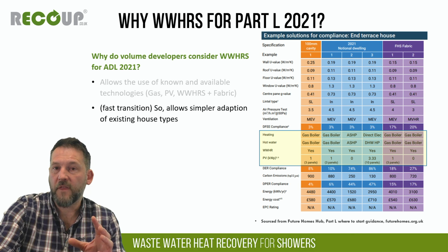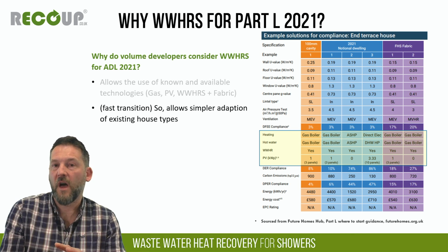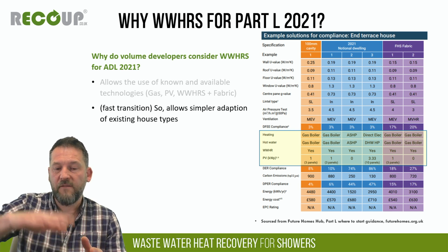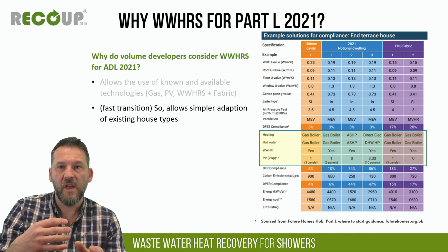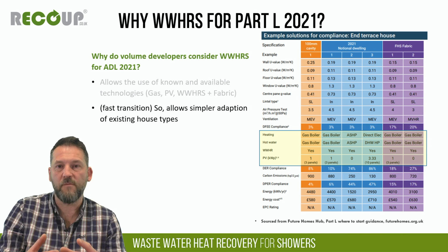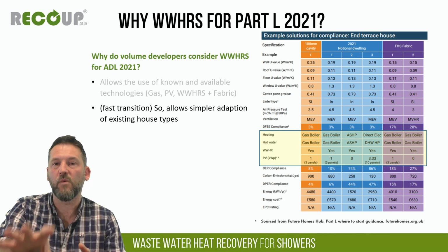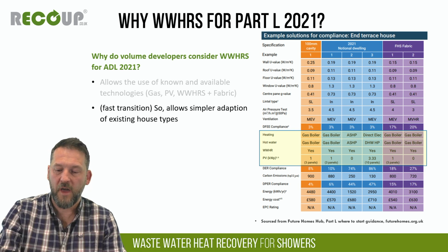Not necessarily for the SAP points with air source, but because of the secondary benefits. By significantly reducing the amount of hot water demand, it tends to even out the seasonal spikes in hot water demand that tend to test air source heat pumps often. So it allows for smaller cylinders to be specified, reduces short cycling, and has lots of other secondary benefits. So it really is worth looking at if you're considering air source and other electric heating and hot water solutions as well.